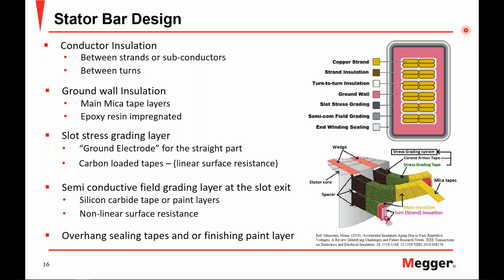Now, it's important to have a good understanding of the stator bar design because, as we'll look at later, the phase resolved partial discharge pattern generated from a partial discharge measurement gives insight into the type of defect and its location within the insulation, which in turn reveals the severity of the defect.